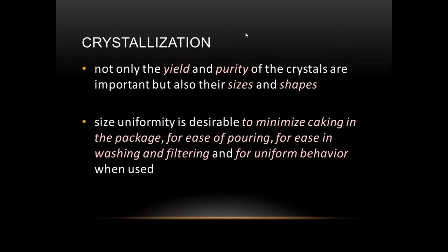To minimize caking in the packaging later, for ease of pouring, for ease in washing and filtering if your crystals are to be processed further, and for uniform behavior when they are used. So it is important that the sizes of our crystals be uniform. Primarily in the case of packaging, this concern with caking, in the case of pouring, and in the subsequent processing of your crystals during washing and filtering, it is very important that they are of uniform size.